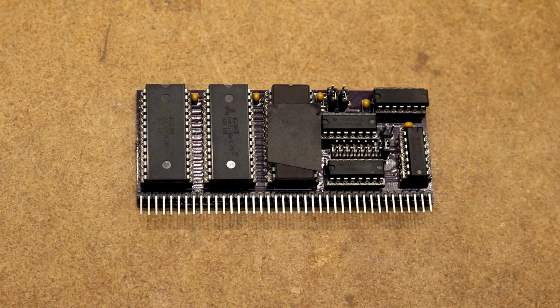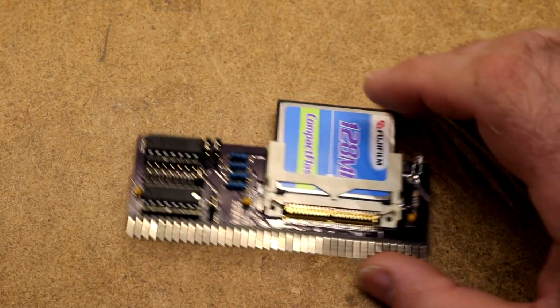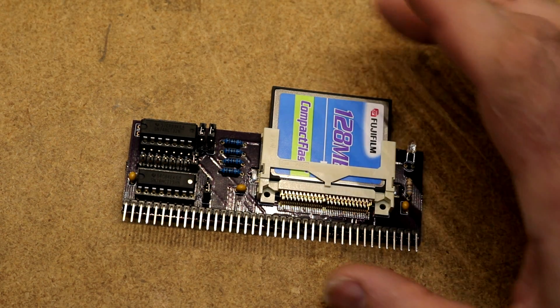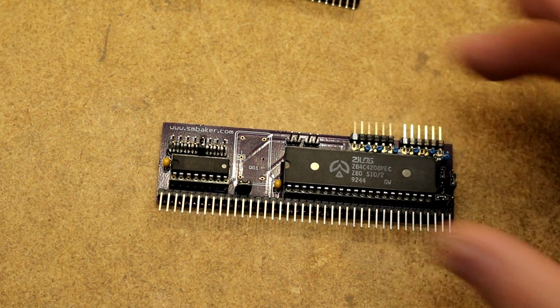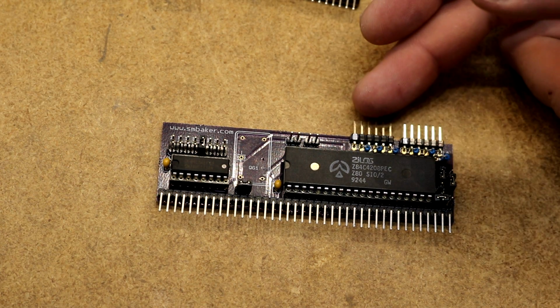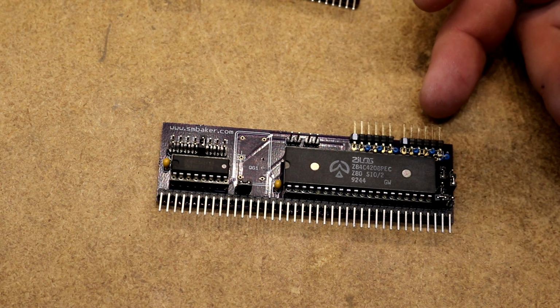Okay, to get CPM running, we're going to use 2 more boards that I've covered in previous posts. That is the compact flash board and the SIO board. I'm not going to describe these 2 boards in this post because they've already been described, but you'll need the compact flash board for storage, and you'll need the SIO board for serial I/O. The SIO has two different serial ports on it. You only need to use one of them, and the way I've set it up, you just plug an FTDI header into it.